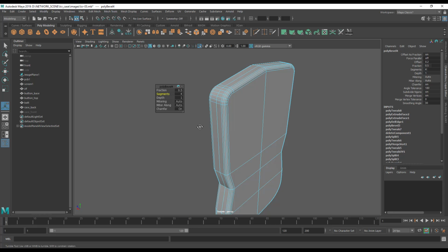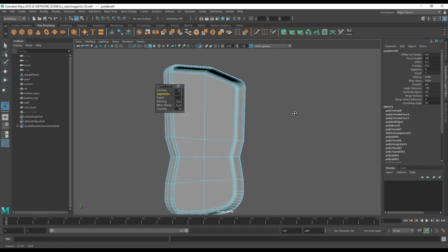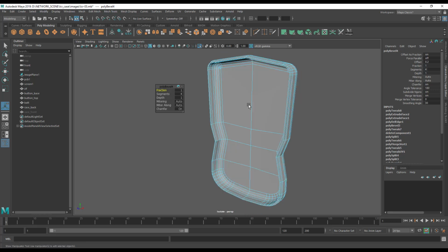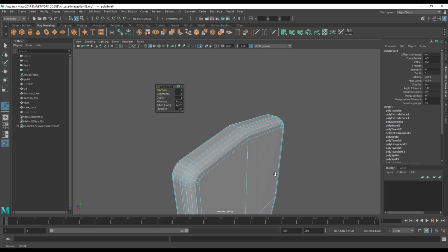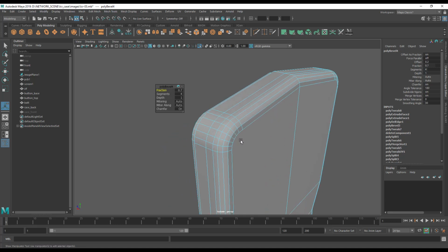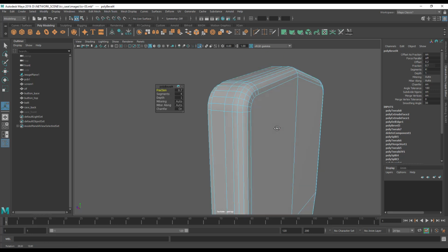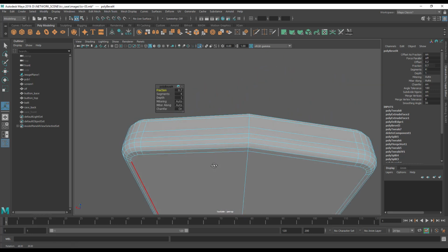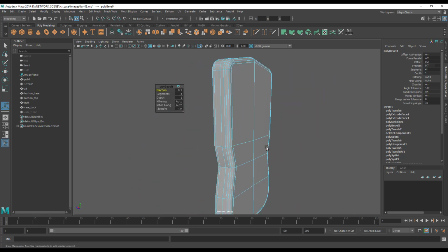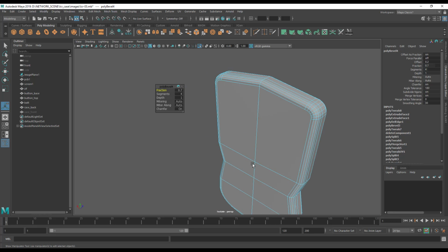Let's create some more segments here. I should create them on the inside too. And let's perhaps get a bigger fraction. Now you can see we can do a bigger fraction now, because as we do this, the inside also changes. So we should keep that uniform thickness. I don't want quite that much of a fraction, however, because I am going to be 3D printing this thing. So if I get too big a rounded edge, of course, then I'm going to be 3D printing with supports, and I don't want to print this with supports, so I'm going to keep that to a minimum.